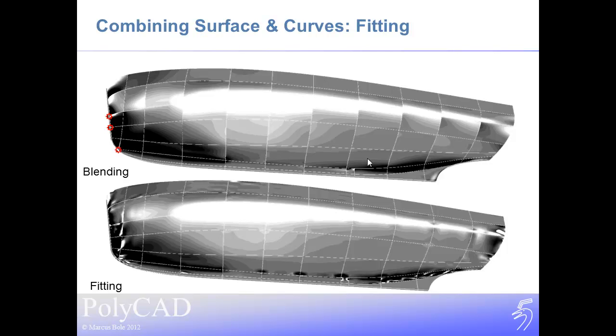And the bottom case is if we take the lofted curves and sample them and generate a surface using our least squares fit. Even though both of these surfaces have the exact same definition, the bottom surface here, illustrated with Gaussian curvature, is a lot smoother in the way the patches are generated. That said, we have a few problems around particularly small patches in the second case at the bottom.